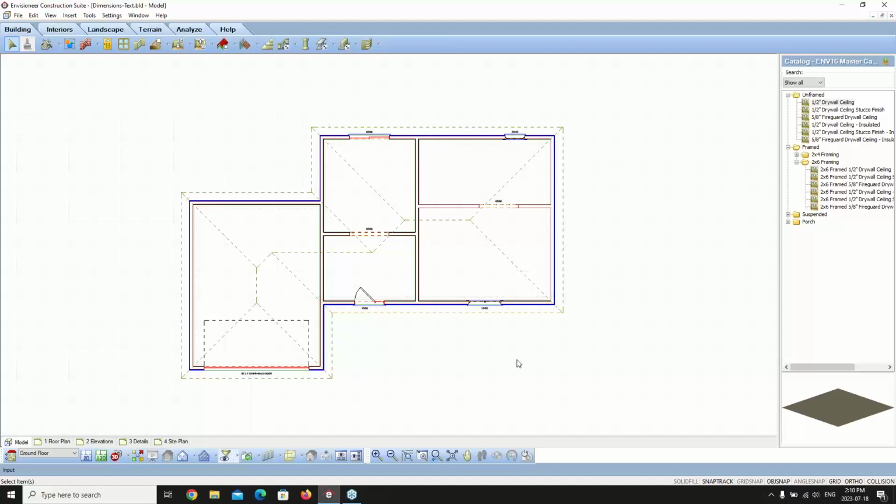And now we're going to be talking about adding in our automatic dimensions. So the auto exterior dimension tool will automatically dimension the exterior walls of your design. By default, 3 dimension strings are created, one for your openings, one for your wall segments, and one for the overall dimensions on each side of the model, like we show in our dimension settings.